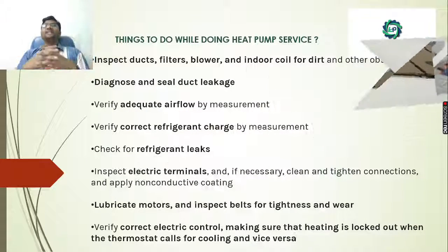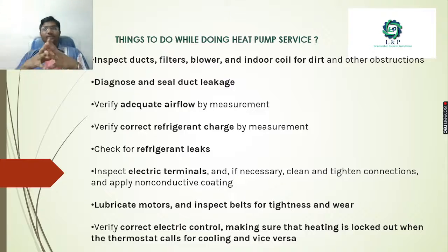And what are the things that we need to do while doing a heat pump service? Same as an air conditioner, we need to inspect its ducts, filters, and blowers, and also check the indoor coil unit. Is there any dirt or not? If there is, we need to remove it. We also need to diagnose and see if there is any leakage in the ducts, and check the airflow measurements. With the help of airflow measuring devices, we can check whether we have adequate airflow or not. And we need to check the refrigerant charge, whether it is fully charged or not, otherwise we need to recharge it.